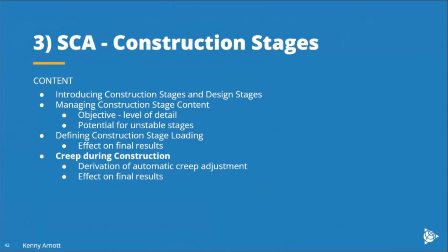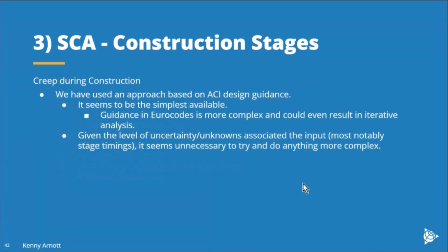Okay, we can now move on to looking at creep during construction, and again look at how that has an effect on the final results. So in terms of creep during construction, start by saying that we've applied the simplest approach that we could really find. It's based on the ACI guidance. That gives us good guidance that's simple to use and can be done in a non-iterative fashion.